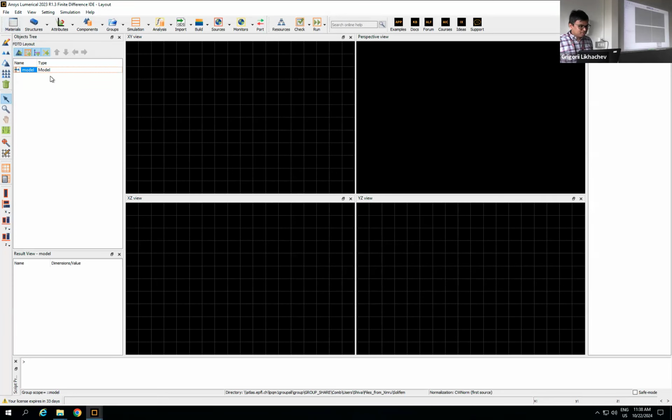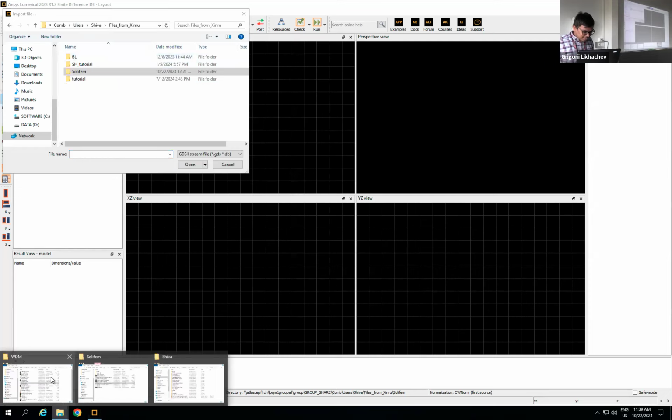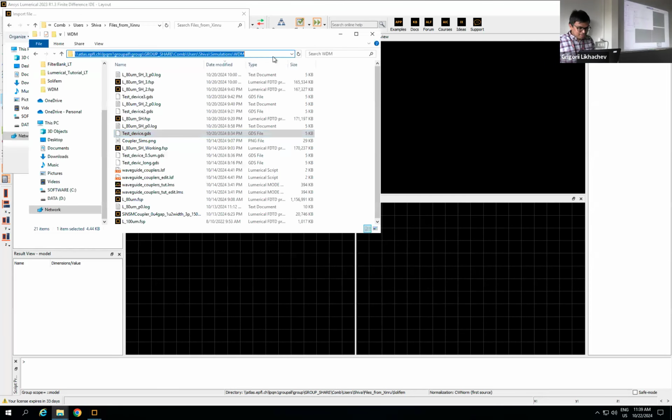And then what you need to import next is the GDS file. There is an option that you can see on the top of the screen. There are different structures that you can draw or different components that you can add. But you would be interested in importing the GDS file, because you can draw any design into your GDS file that you usually would, and then finally import it. So you have the option on top called import GDS, and then you can import the file.